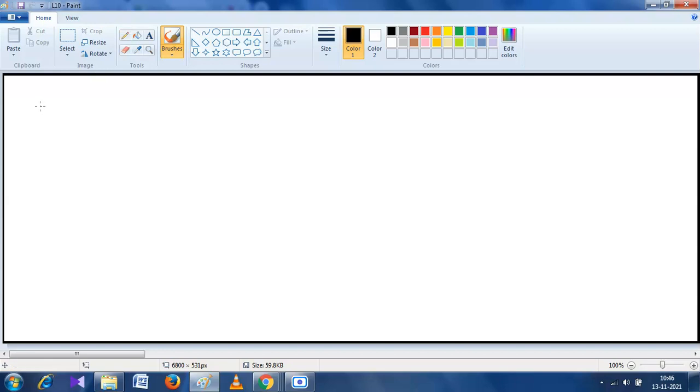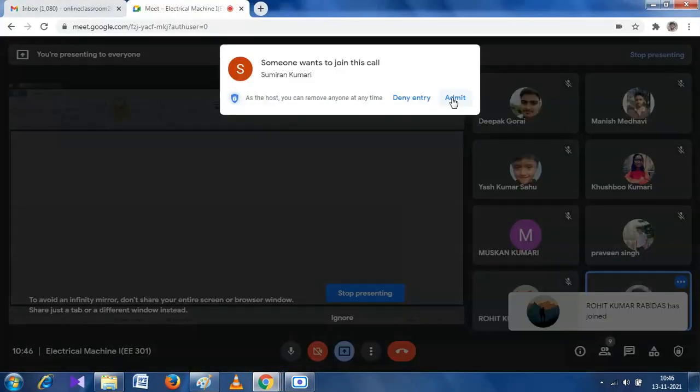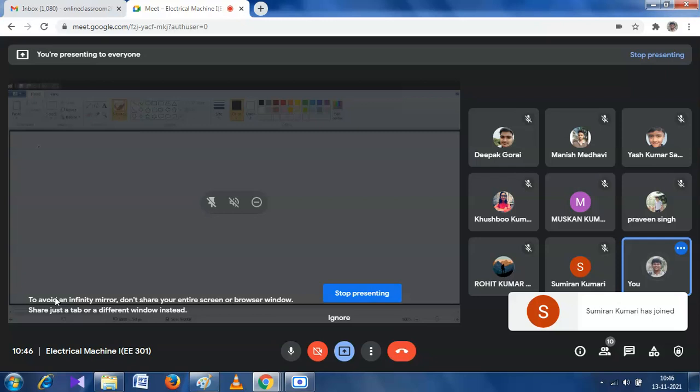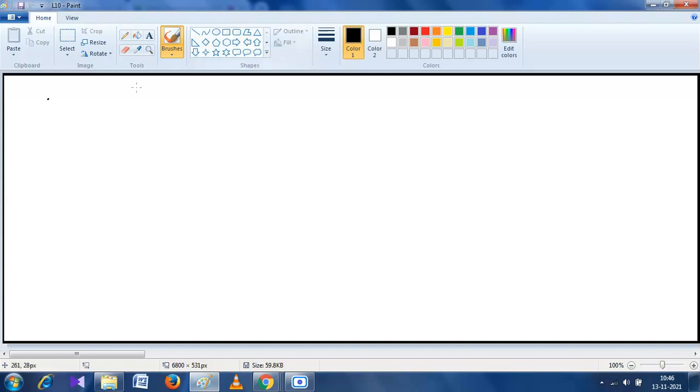Now, tell me, what is the torque equation? Tell me anyone. What is the torque equation? T is equal to K phi Ia. And what is the speed equation? N is equal to V minus IaRa by K phi.